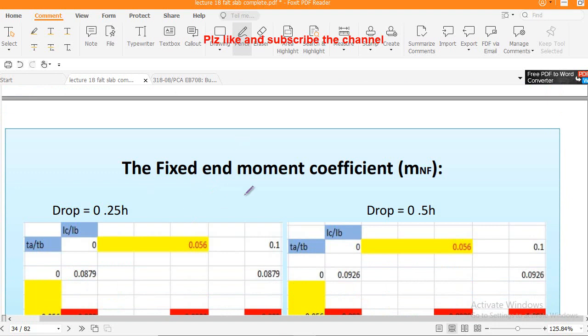This is the calculation which I already explained to you people, and I will show you how to find the coefficient to calculate the fixed end moment. You must already know, when we use the fixed end moment in your undergrad, I think you must have learned that we will use 1/12 WL squared, I think.